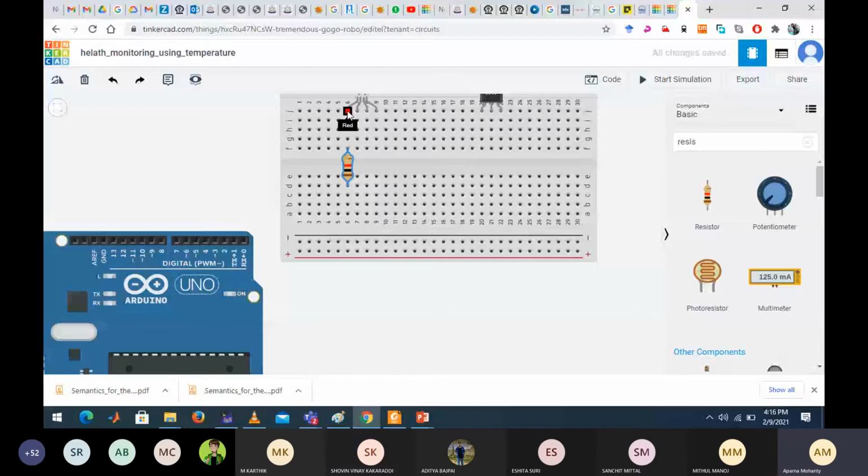Yes, everybody? Okay, just move your cursor a little bit. What is written here? Red and cathode. So that is the cathode terminal of your LED. Okay, just move one more. It is blue. Okay, next is green. So this red, blue and green are the actual terminals of the LED, and this is the cathode terminal. Okay, so I need not make a connection of resistance to this cathode terminal. So I need two resistances to be connected here.